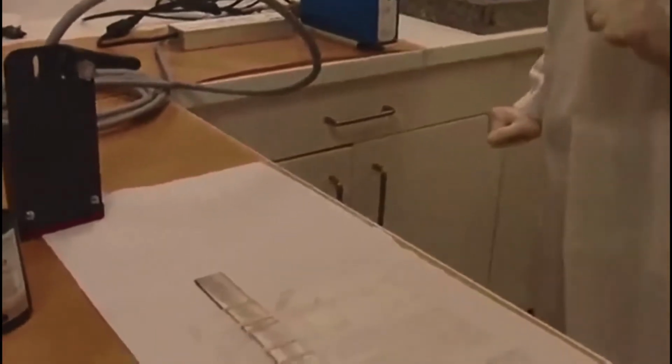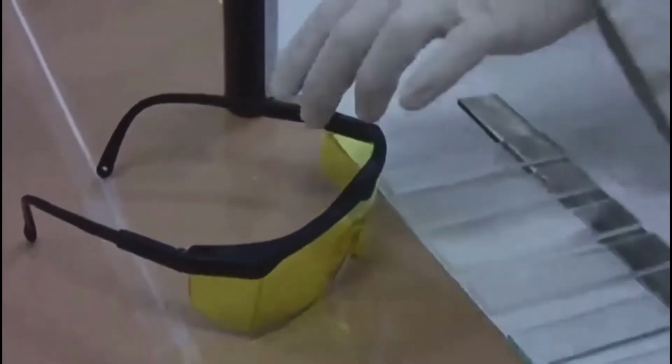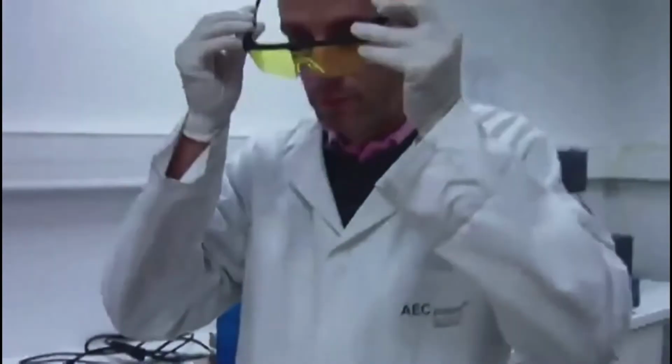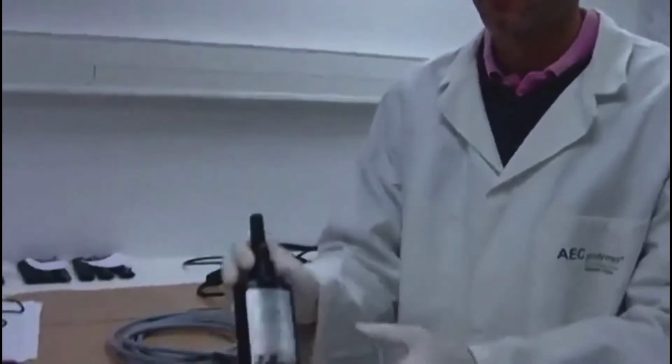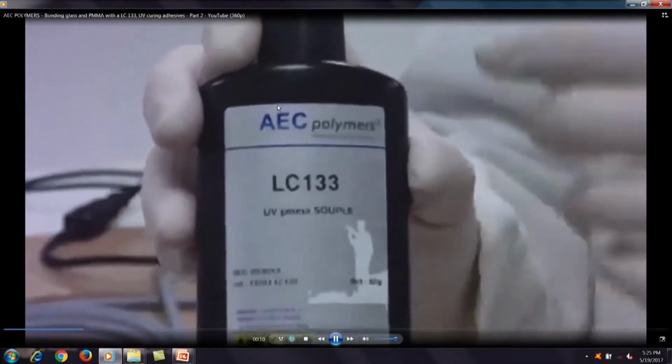And the joint is ready. So you can see that no pressure has been applied in this case. The two adherents have been taken, in between we have placed an adhesive, and after the adhesive has been applied, the curing has been done using heat. So that is the basic, most simplistic type of joining that has been done.